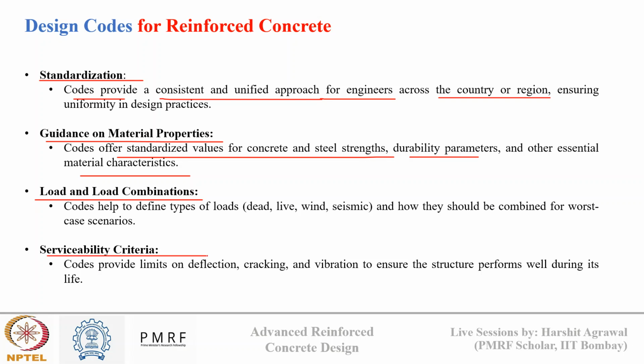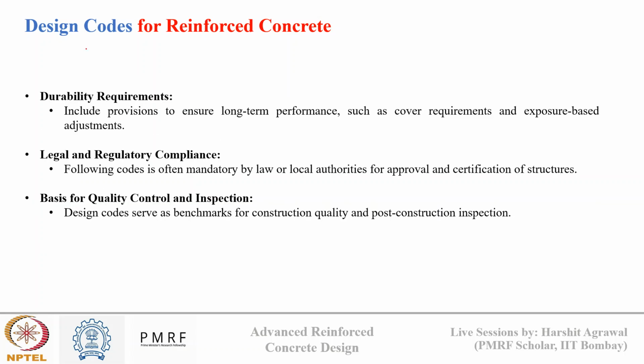It provides us the serviceability criteria so that we can limit the deflection, cracking, and vibration in our system. It provides us the durability requirements, which helps us to ensure that our structure performs well over time also. It provides us the legal or regulatory compliance, like following codes is often mandatory by law and local authorities for approval and certification of the structure.